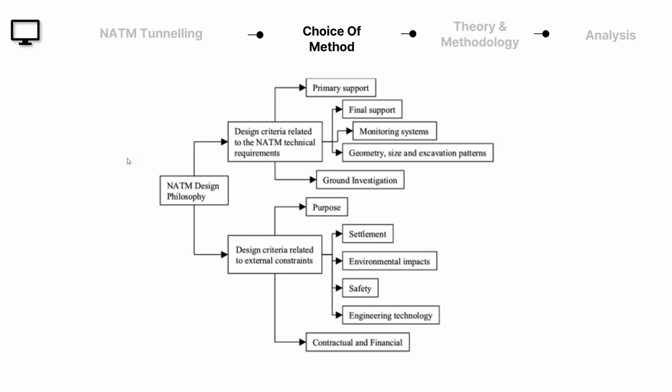And NATM, as we all know, is basically like you see, you monitor, and then you improvise on site. So it is mostly an improvisation based process. That is why in NATM methodology, monitoring is the paramount thing that you have to take care of.